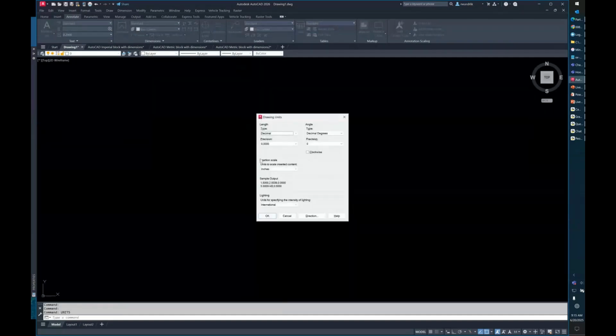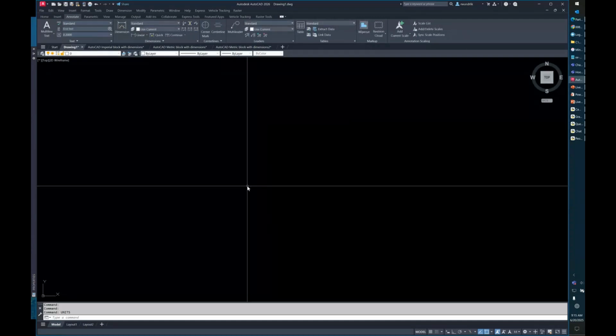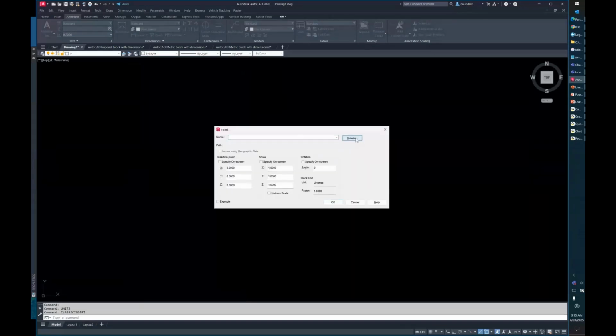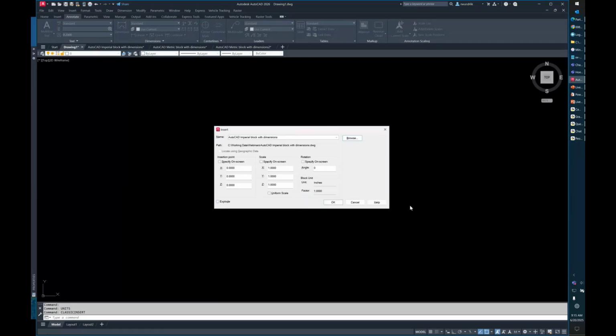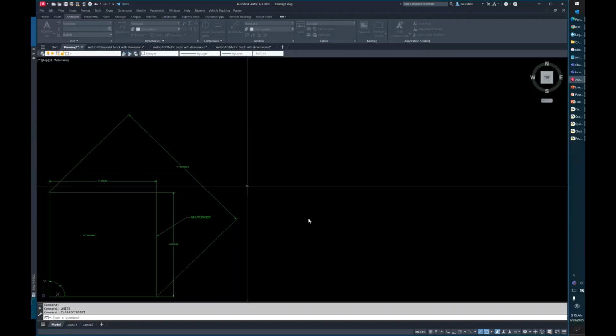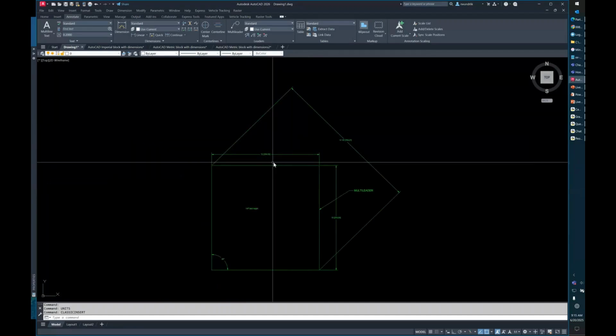And I'm going to see that this is a decimal set to inches, which is fine. I just want to show that this is set to inches, which means when I go to Classic Insert, and I go select one of those drawings, right? We'll do the imperial. You're going to see that it tells me that the block unit of this imperial drawing is also in inches, which means there will be a scale factor of 1. I'll bring it in, and we're here. And I can do the same thing again.